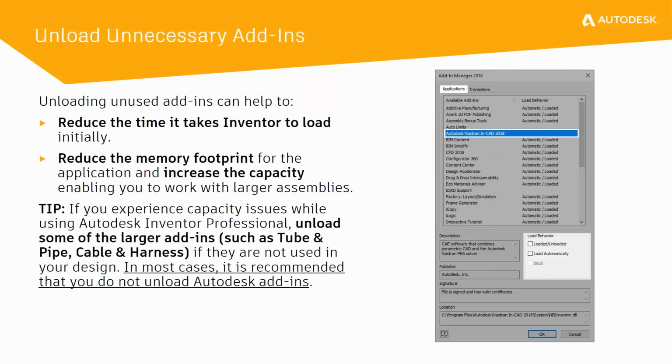Some other things that you can do is unload unnecessary add-ins. I spoke earlier about memory. Each time you load Inventor, it is likely going to be loading a whole bunch of different add-ins in the background, some of which you may not necessarily be using on a regular basis. In this instance, I've highlighted Nastran In-CAD, but there might be other areas, the factory layout.